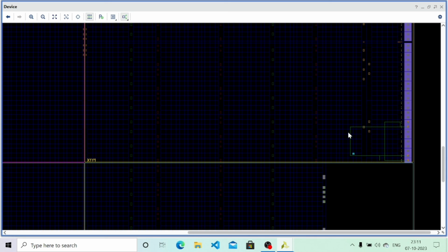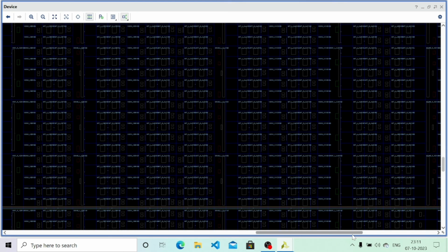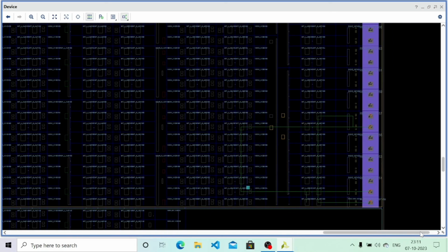So these are the connections that are being made on the FPGA. Before they were not there, right? That is the usage of an FPGA: by definition it is a blank slate, and whatever circuit you want to realize, you can realize. By zooming in more, you can understand which LUTs are connected and how they are being connected.